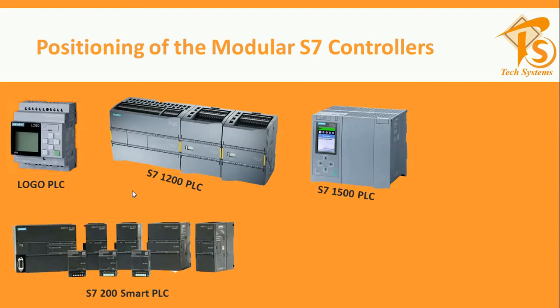Now the next version is the S7-1500. It is the upgraded version of the S7-1200, and it has a built-in display. You can see there is a display here, and here there is no display, so it is blind. If any fault occurs, you see the error LED, go to the software and open the diagnostics. But here the display is there, so if any fault occurs inside any module, you can see it directly on the display. This is a very unique feature, and it is not provided by all PLCs. It is also used for process plants, manufacturing units and machines, and it is also a compact modular series.